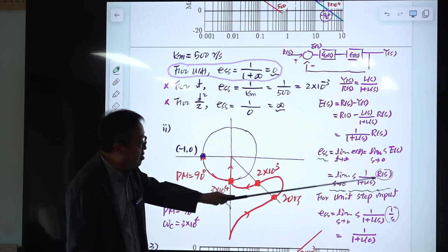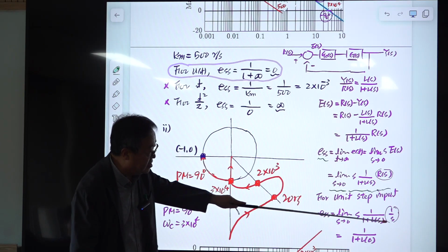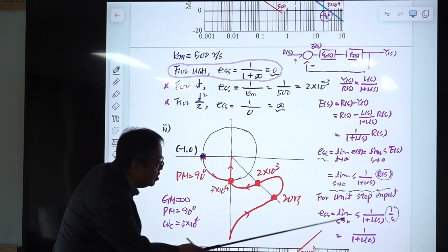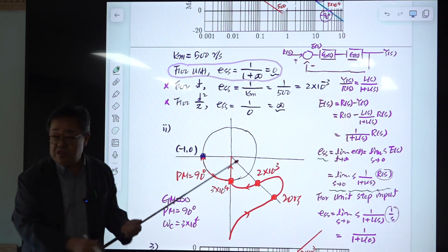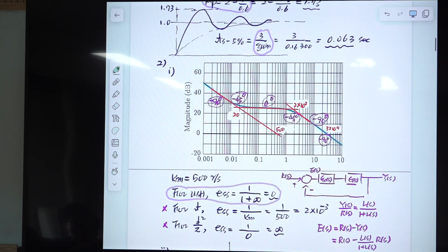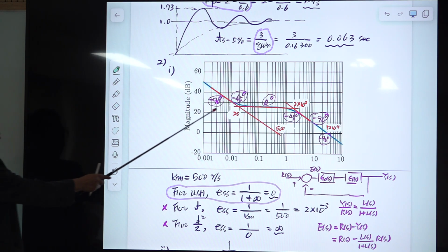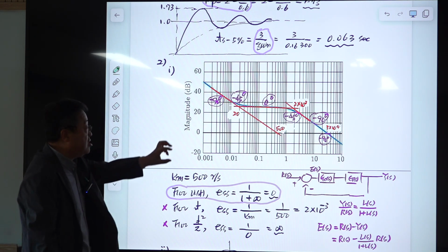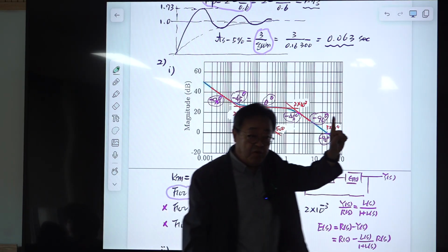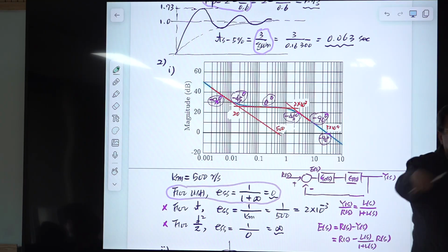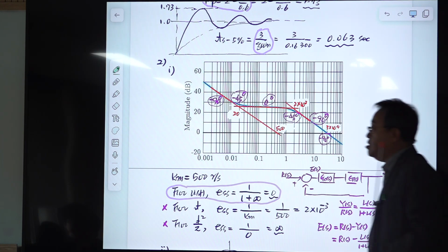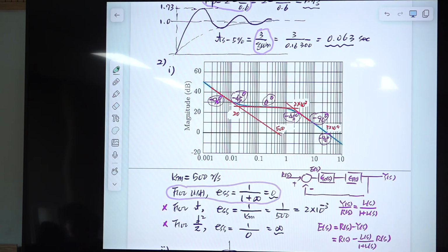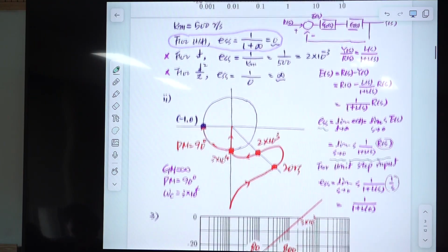For the step unit, you just use 1/s, and the S's cancel. All right. Then you evaluate this at 0. Then you have this original integration, and this pole at 0 has terms, but these terms reduce to 1. All the terms other than this initial integration become just 1 because we are using s = 0. Okay, for the final value theorem, this is very trivial. There's nothing to remember or nothing to memorize.